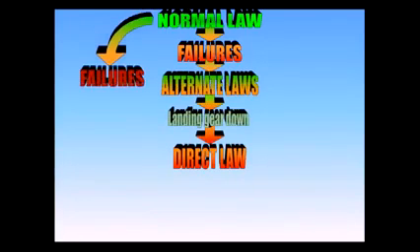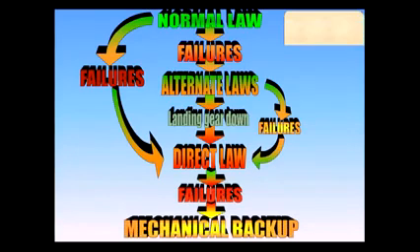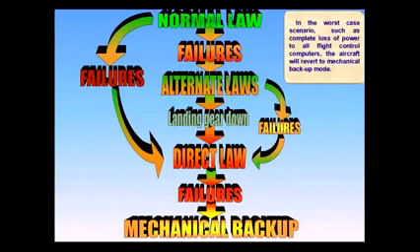In the worst-case scenario, such as complete loss of power to all flight control computers, the aircraft will revert to mechanical backup mode. In this mode, pitch control is accomplished by manually trimming the stabilizer by using the pitch trim wheel. Some pitch control can also be gained by use of thrust.